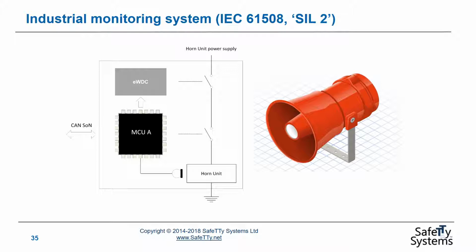So this part of the industrial monitoring system would be developed in compliance with IEC 61508 at SIL 2 level, and could be done quite happily using a single microcontroller and external watchdog device running a time-triggered architecture.